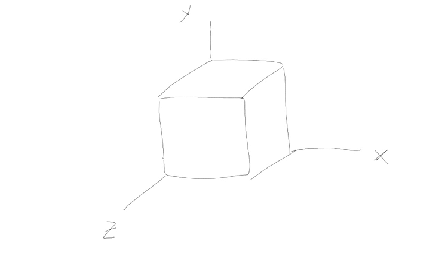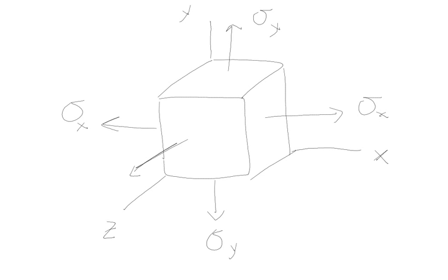Now, keep in mind that this is just a single point on my object, so it's a tiny, tiny cube. So think about what happens here. If this cube is being stretched in the x direction, what does that mean? It means I've got sigma, or normal stress, in the x direction. If this cube is stretched in the y direction, it means I've got sigma sub y acting on those top and bottom faces. What if this cube is being compressed or stretched in that z direction? It means I've got sigma z. And you obviously can't see the one on the back, but it's there, okay?